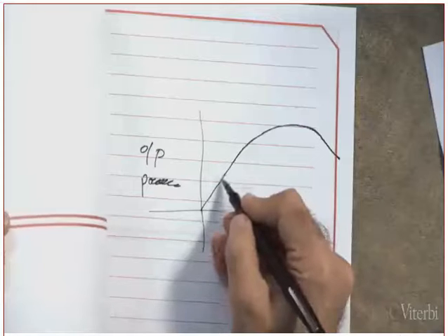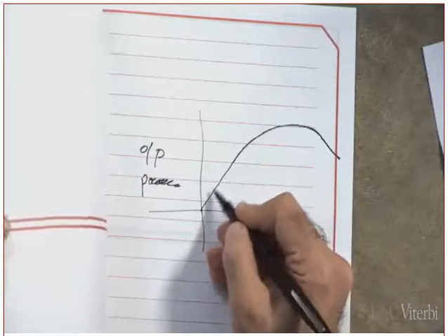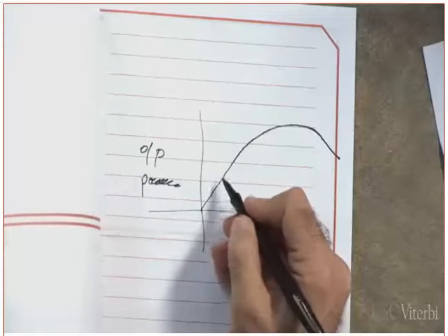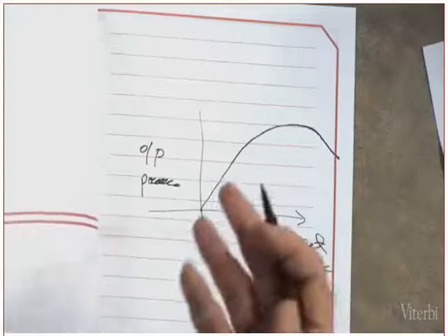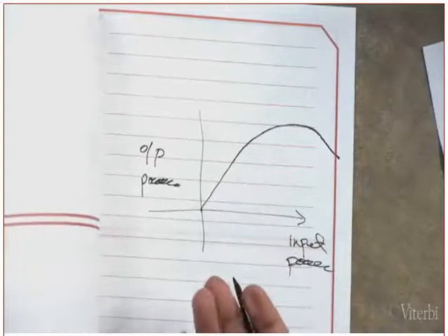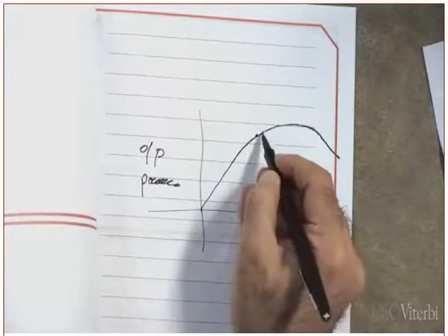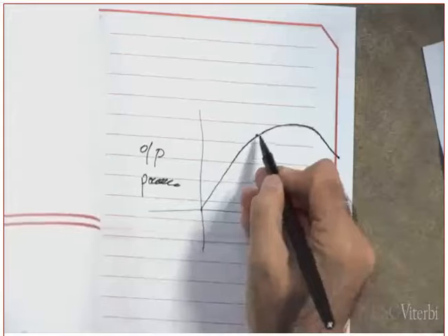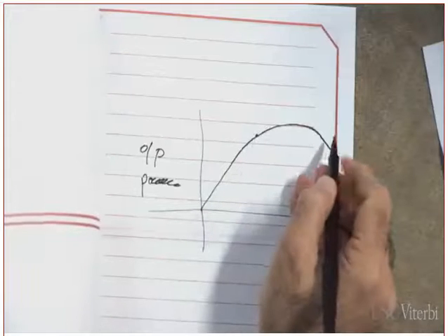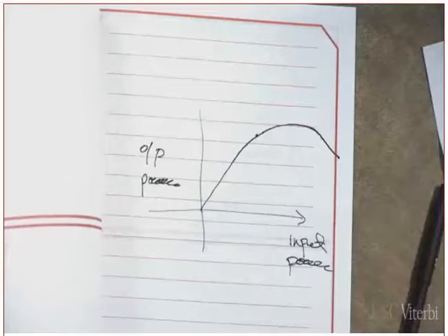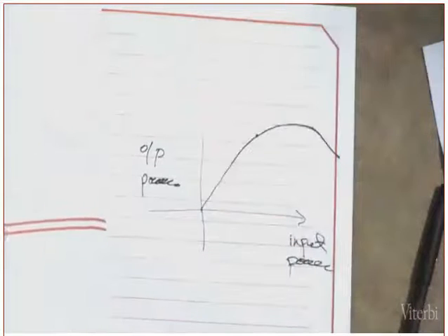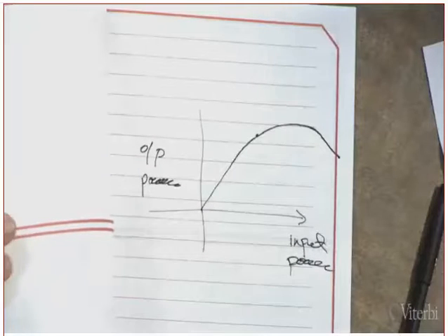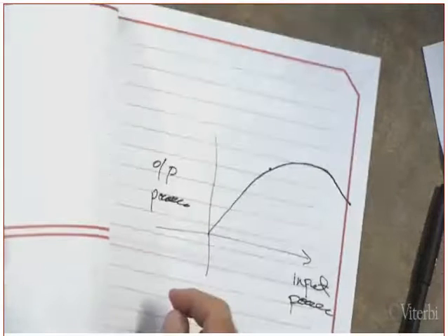But I also don't want to operate in here, because in here the efficiency of the amplifier becomes lower. I want to operate the amplifier closest to the maximum efficiency. So I would like to operate it here, somewhere in here. Now keep in mind, once you get non-linearity, all the side spectrum, all the side lobes that you get rid of using filtering will come again, will regrow again. Do you understand? If you do have non-linearity.